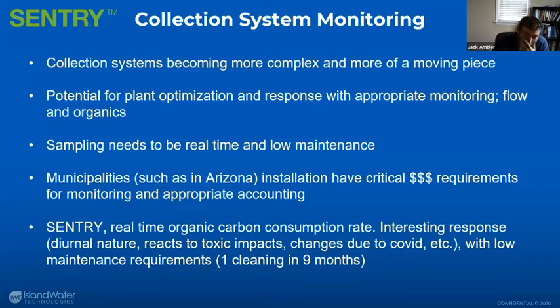You need to know how much is coming hydraulically, and whether you have any bad actors, from organics or inhibitory compounds that might screw up the plant or might highlight some illegal or unintentional dumping. Sampling needs to be real time and low maintenance. These are difficult locations to get into, and the value of getting the data ahead of time is only valuable if you're getting it ahead of time and not after the fact.